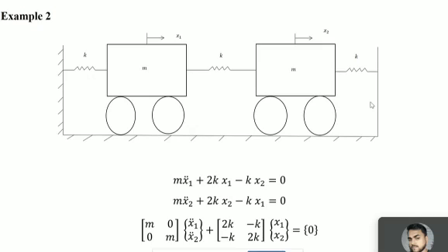The vibration is so complicated that there can be a large number of modes, but the first mode we cannot define properly, and the first natural frequency is zero. We have to eliminate them. There is a sweeping out procedure.